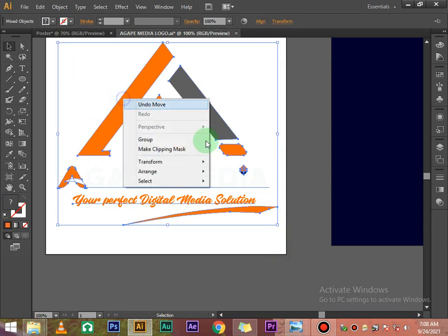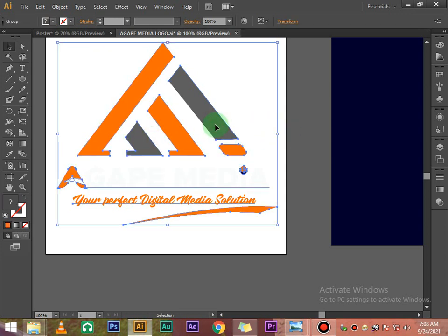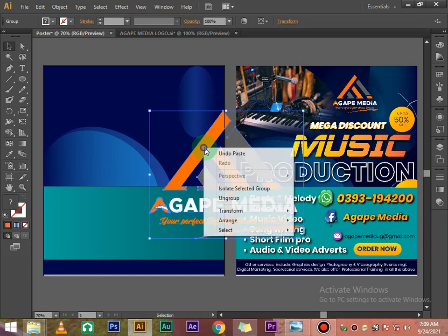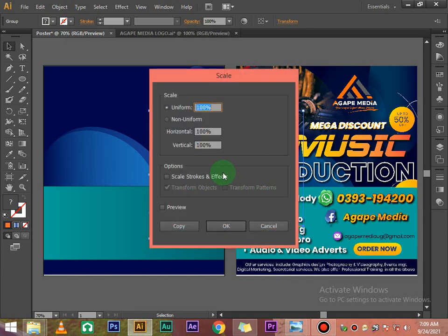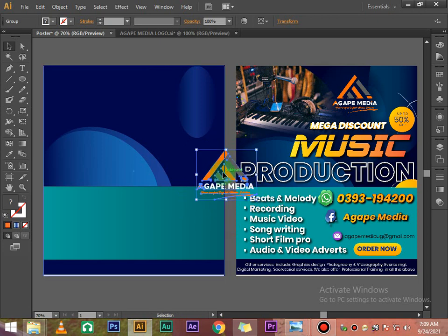Logo, the entire logo. I will group it. After grouping it, I press Ctrl C to copy. Then I come onto my work where I'm working from. Then I can press Ctrl V to paste, but now I'll have to resize. So I'm going to transform, then scale. Okay, then reduce, let me say 90%. Then I just press Ctrl D to continue doing that until I get what I want, assuming that's the size.